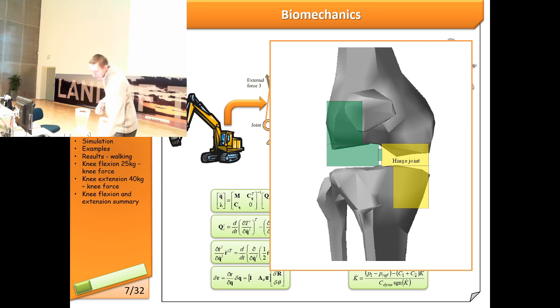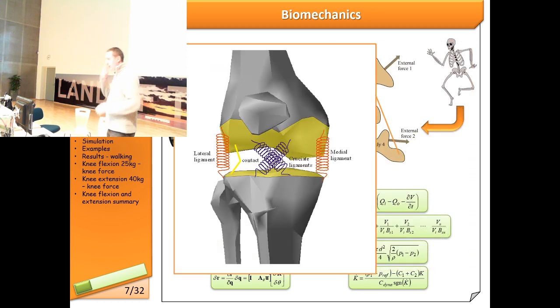So what you can do then is go to a little bit more accurate model, and you can have two surfaces, marked yellow in this picture, and those two surfaces will be used for contact. So they will be sliding on top of each other. If you model the shape of those surfaces reasonably, then you will get a sliding joint that should behave more or less like a leg. Then, of course, those two surfaces won't keep touching each other by magic. So you can either apply a constraint that is actually causing them to stay one on top of another, and that will be some sort of approximation.